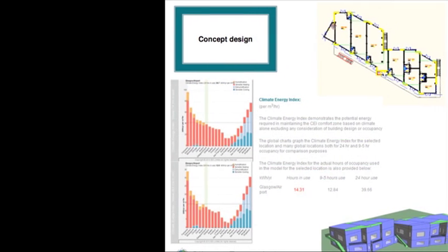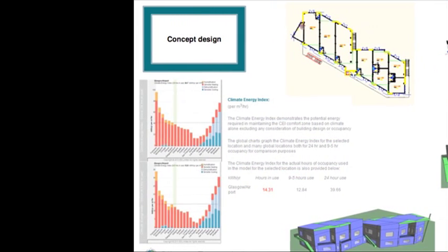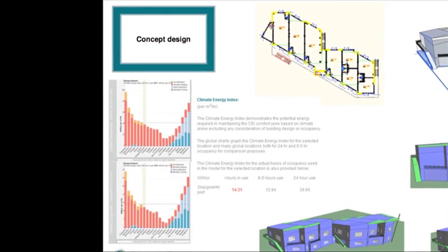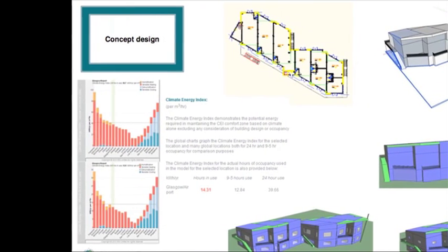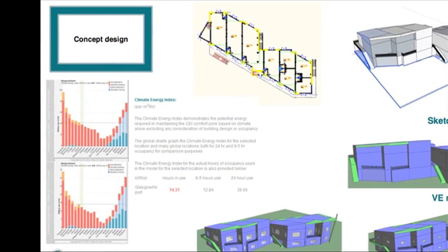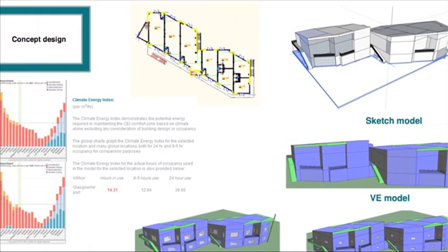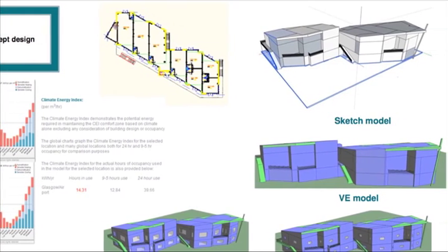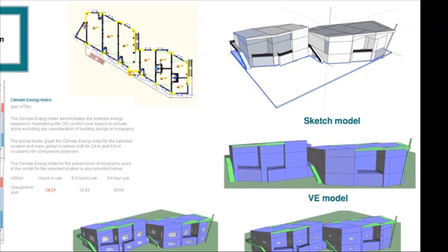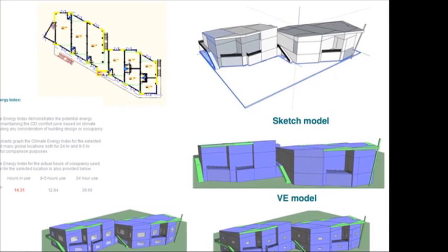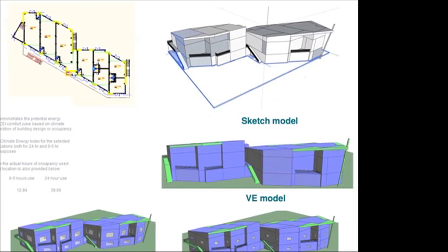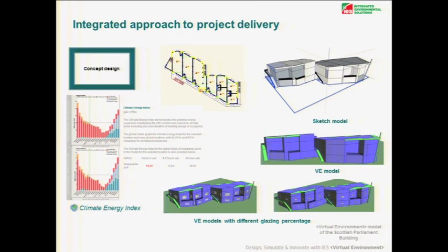Okay, concept design, we may be looking at multiple options in concept design. We'd be getting some comparative studies out of that. So, does a tall model with a fairly compact footprint building perform better than a low-rise version, same gross floor area, which is more dispersed in its footprint? We can start to refine things like orientation, solar shading, glazing percentage, but still at a fairly high level. So making decisions as we get feedback from the model, okay, from the analysis.